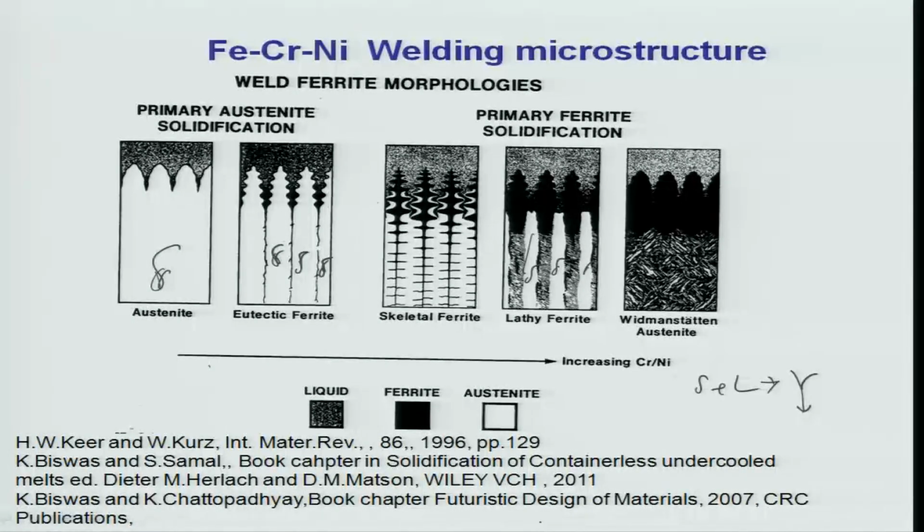On the other hand, this delta is called lath type ferrite, or delta, and the gamma which is already transformed to, gamma will transform to pearlite, because gamma is not stable. Pearlite, that is what you see here, these are pearlite. Okay, but the question is that as the delta is retained in the microstructure, the delta actually creates problems later on, because delta transforms to alpha iron, and alpha iron is a soft phase, and not only that, it leads to volume expansion. So therefore the welds crack during solidification. So this is a typical problem of peritectic reaction in stainless steel welding.